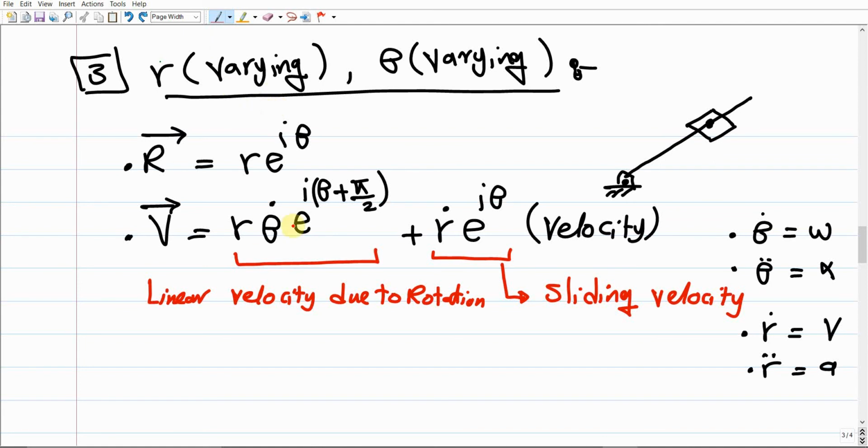So what does it mean? It means we have two components of the velocity: one that describes the sliding velocity of the slider itself, and a second one that depends on the rotation of the link itself. So one is related to the link and the other is related to the slider. But we should keep something in mind here. Let us give some names to these points. Say this is point A and this is point C. So there should be a position vector here.